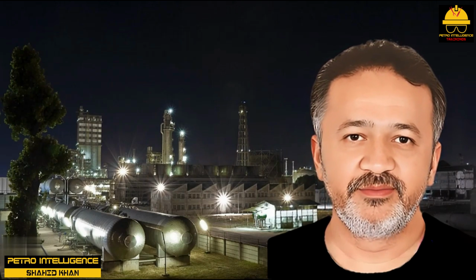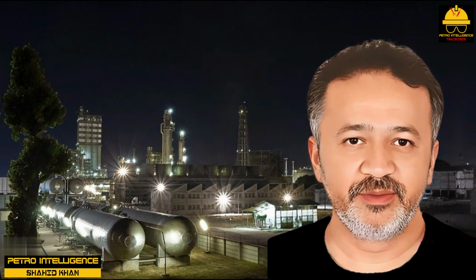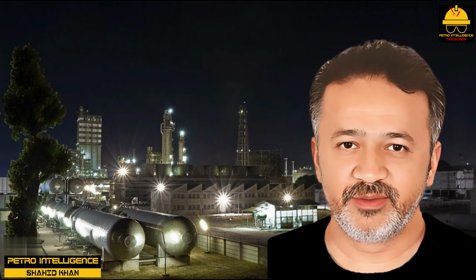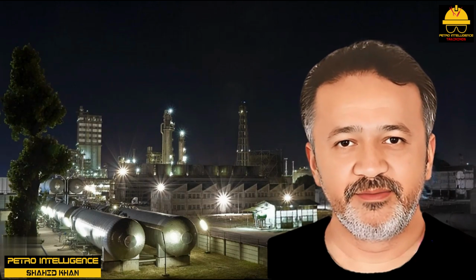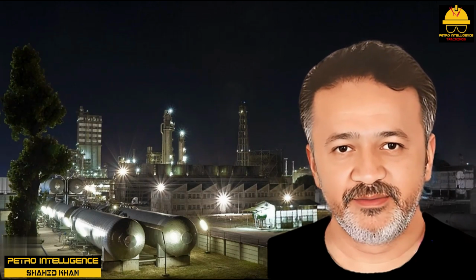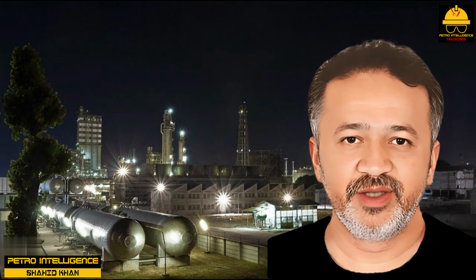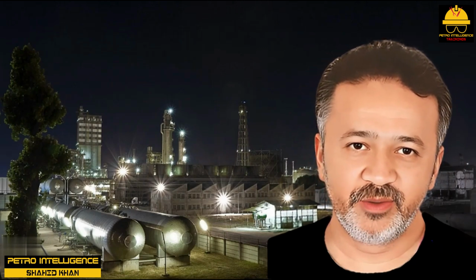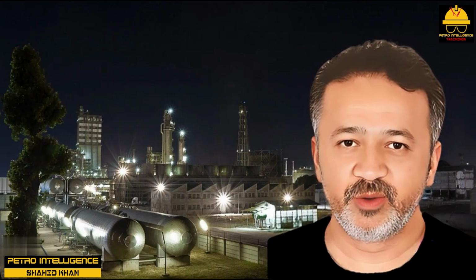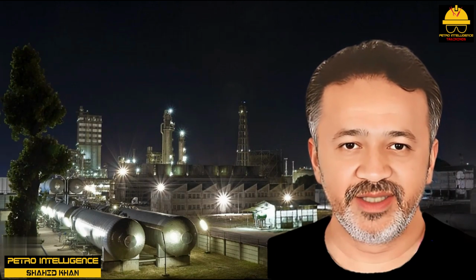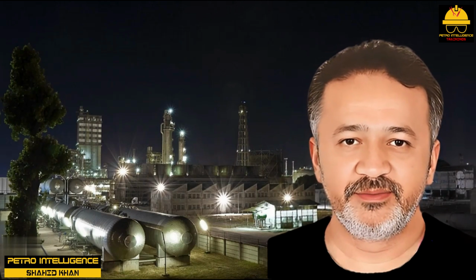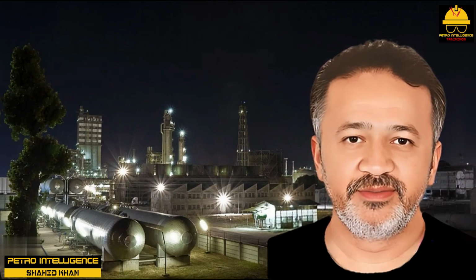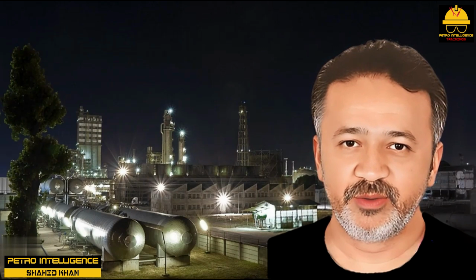Runaway reaction. In 1968, a 3,000 psig vessel exploded. This unhappy event occurred at the ESSO refinery in Bayway, New Jersey. The cause was a runaway reaction. Tar was being hydrocracked in an ebullated bed of catalyst. The reactor got hotter, more hydrogen was consumed, and more exothermic heat of reaction was generated, which increased the rate of hydrogen consumption, which released more exothermic heat of reaction. I suppose if hydrogen feed had been stopped sooner, the runaway reaction could have been controlled. But it wasn't, and the reactor blew apart.